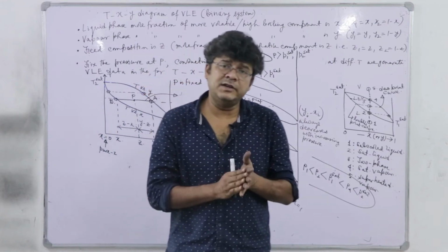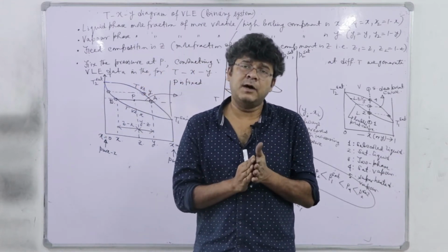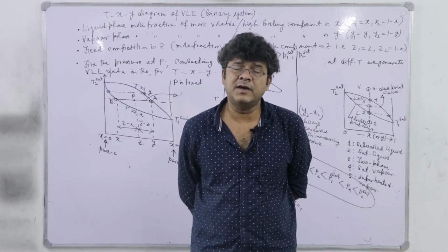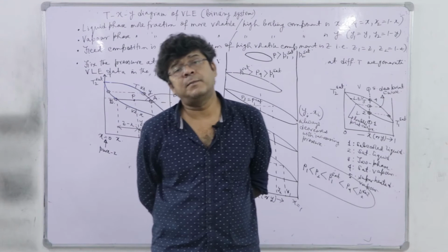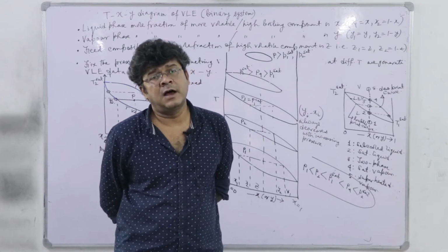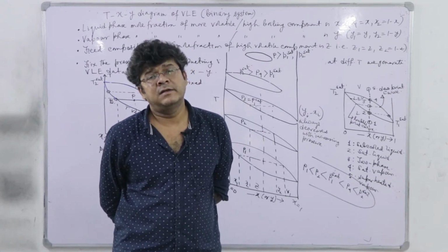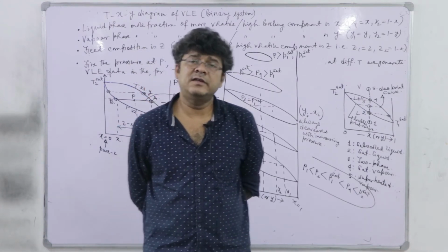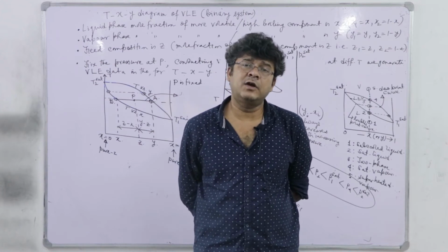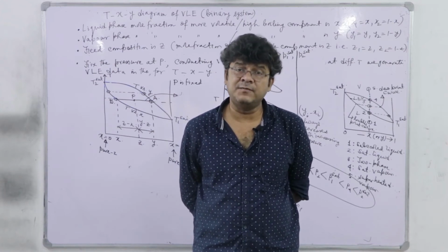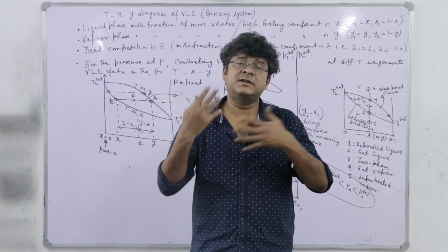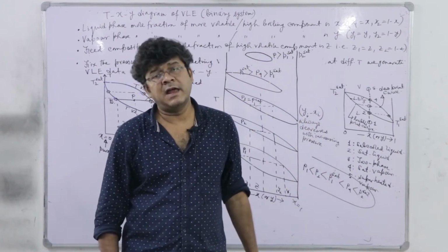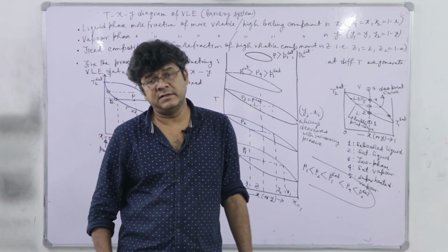So the reduced crude oil, the bottom residue of the atmospheric distillation unit in a petroleum refinery, is further separated into lube oil feedstocks like gas oil, spindle oil, intermediate oil, heavy oil, etc. This can serve as a lube oil feedstock and alternatively as the feedstock for secondary refining. We know that this can be further catalytically cracked or thermally cracked to generate more valuable products like gasoline or diesel. Okay.